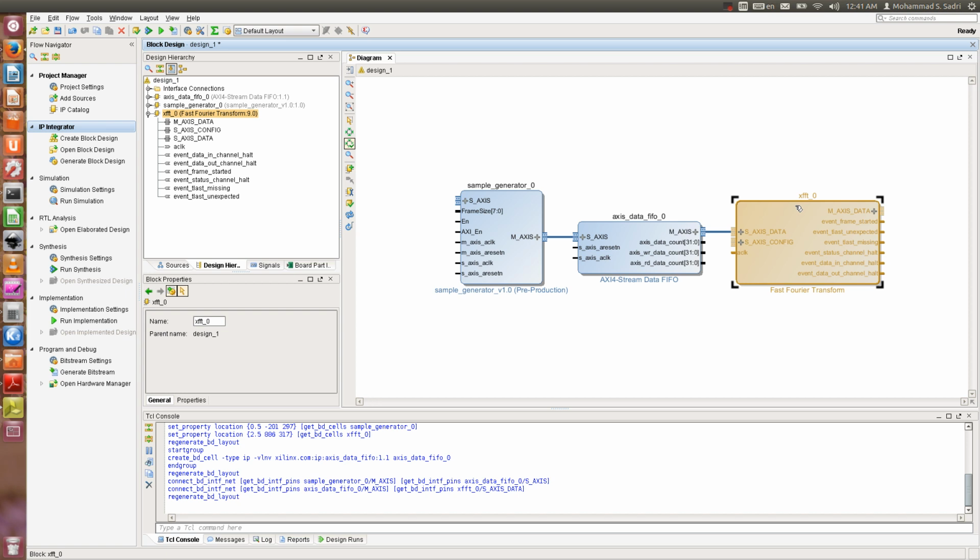As I told you in lesson 8, there is a DRAM controller at the PS, and usually you have connected some amount of DRAM to this DRAM controller, and the ARM hosts also have access to these DRAM controllers. It's a very good idea to store the data on these DRAM controllers so that later the ARM hosts can also have access to the processed data and do their own additional tasks.